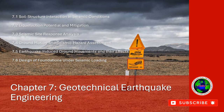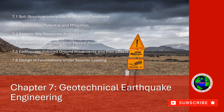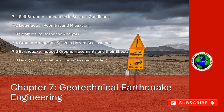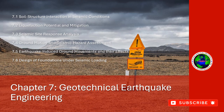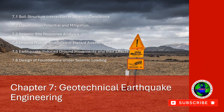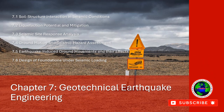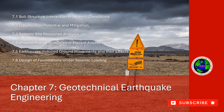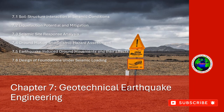Their design needs to account for potential soil displacement and ensure stability during seismic events. Seismic considerations: the design must include an analysis of the soil's response to seismic forces, including possible liquefaction, ground settlement, and horizontal displacement. In some cases, the foundation may need to be designed with deeper elements or reinforced to prevent failure.